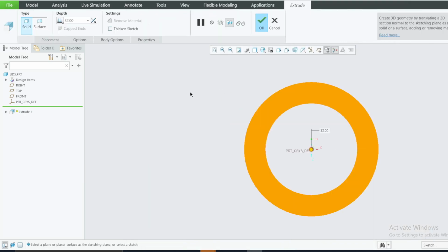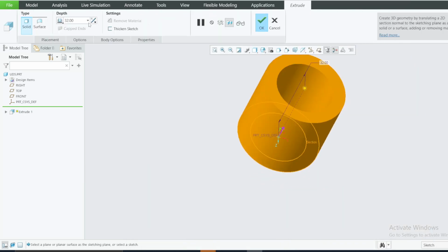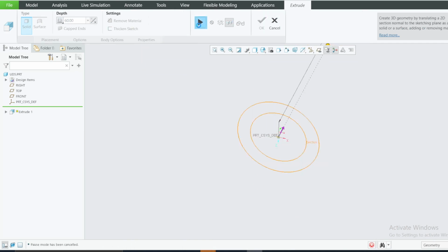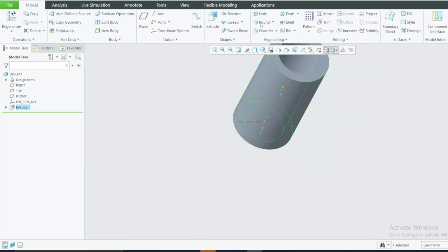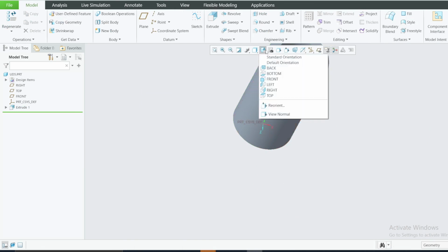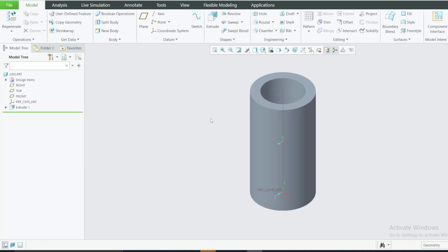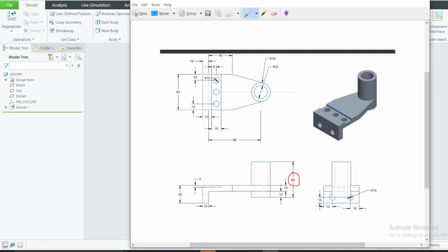We need a height of 60. Therefore, that is our first section. Next is this section here that has an offset of 10 with a height of 10. I'm going to put a plane of 10, then draw this profile, then extrude by 10.